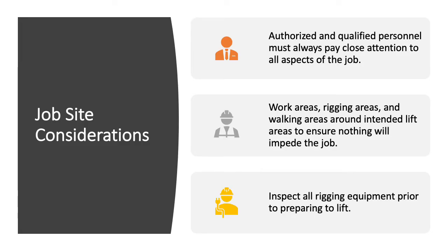We need to make sure that authorized and qualified personnel are the ones that are rigging equipment, meaning you do need to have the certification. Work areas, rigging areas, and walking areas around intended lift areas, we need to make sure that nothing's going to impede the job or potentially get run into with the equipment as we're moving it, etc. And all rigging equipment must be inspected prior to rigging it up.